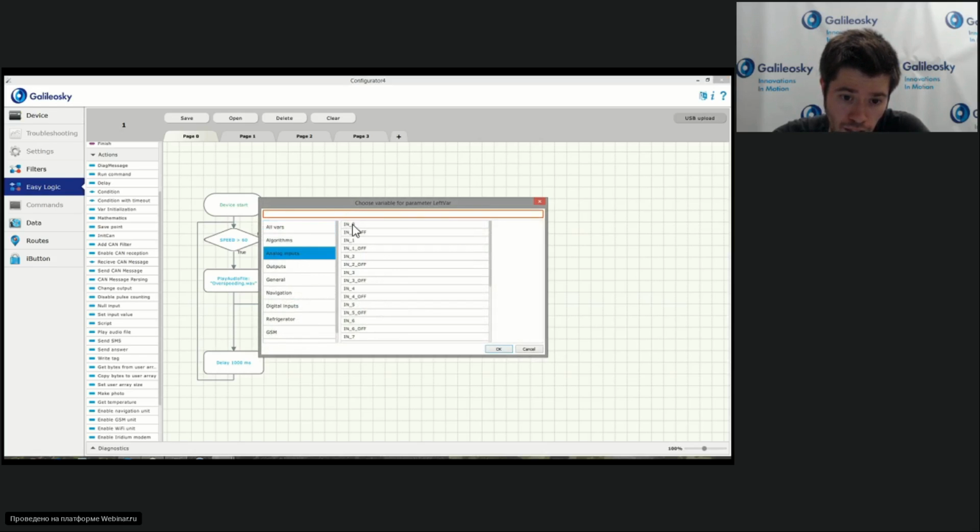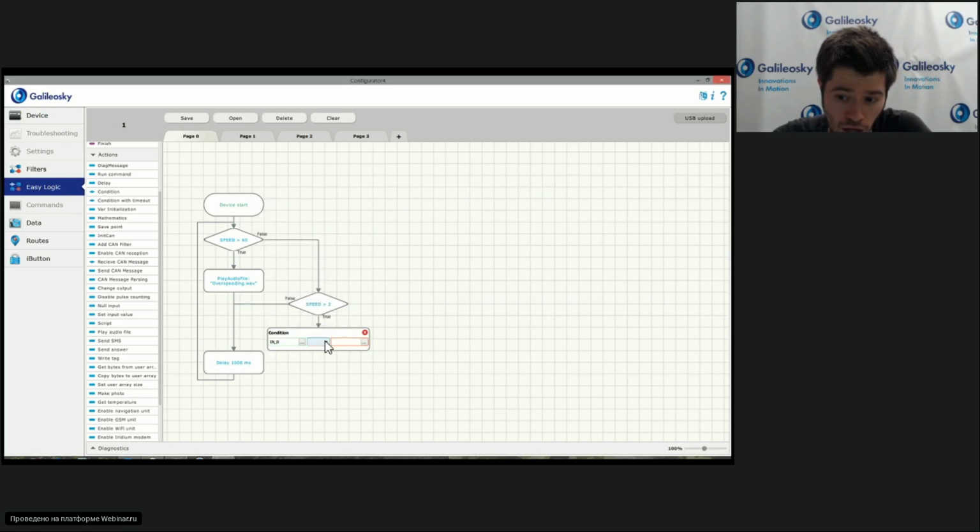We get the input 0 value and check if it's more than, for example, 9 volt. As I already mentioned, 9 volt or more means that the seatbelt is fastened, because then there is some link. If not, then it's not fastened. So more than 9000 millivolt means it's fastened, means everything is correct. We again go here. But if it's not fastened and we have a speed more than 2, then we go